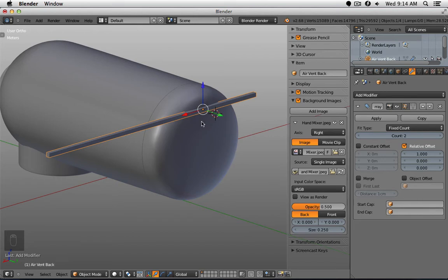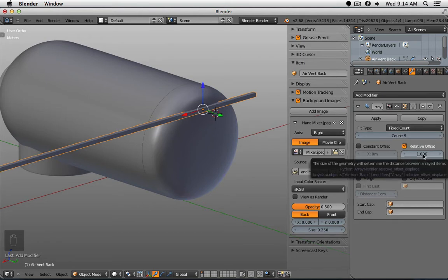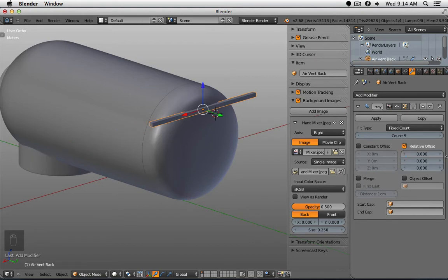So I can see that negative z, that's the direction I would like those parts to be replicated along. So my count maybe should be, let's say, 5. But then instead of along positive x, I type in 0, it should be negative z, and I type in -2.